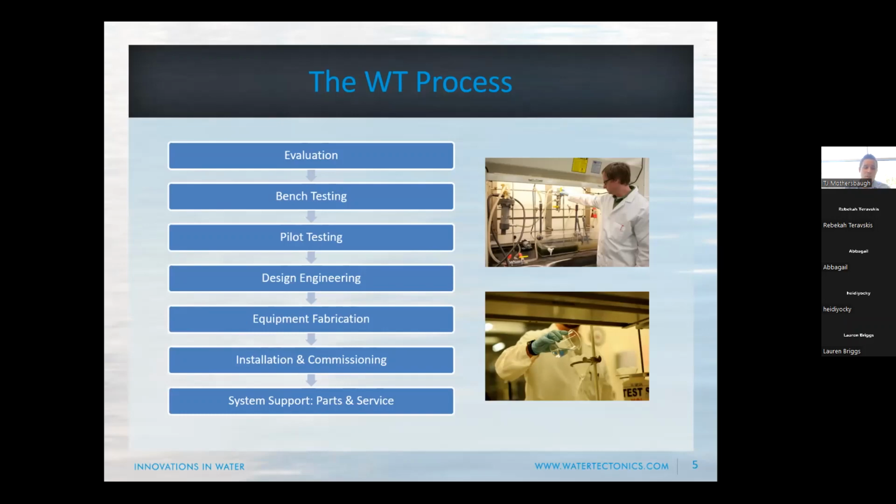From there, we often go to bench testing. So clients will collect a sample of their untreated water and send it to us. We'll actually conduct treatments on it at a small scale and say, hey, this is what worked, this is what didn't, this was the water quality coming in and out of process A, B, and C. These are the things we learned about it. Here's how that would scale up to a full-scale treatment system.